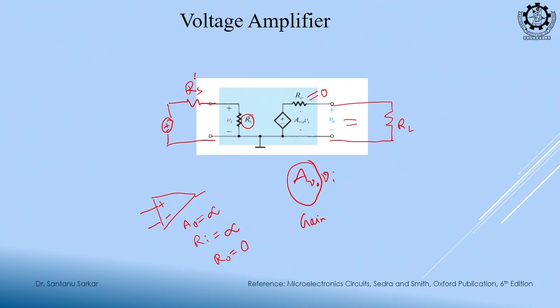What I told you, the internal impedance of a voltage source should ideally be 0, right. So that this Vs totally comes to this Vi, Vi is equal to Vs. So now you can see there is a relationship between Rs and Ri. Why? What is that relationship? I told you that Rs should be much smaller than the load resistance, that time I termed it as a load, right. So that this maximum voltage can get in here. So, to satisfy this, my input impedance requirement is infinite, matching with my logic, clear.